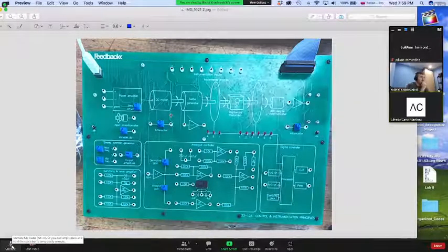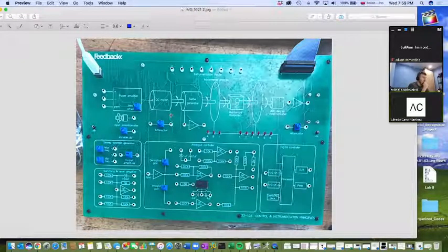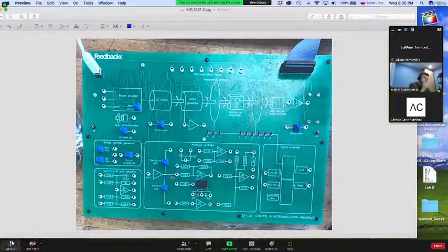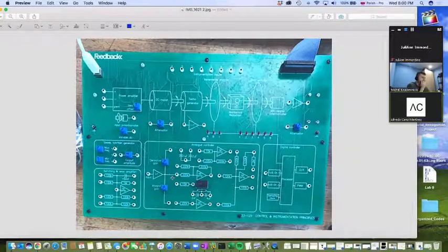So the summing and error amplifier, right? This you usually want to use simply to create the difference, or the error signal. Then you feed that into an additional component. It can be an attenuator, or it can be the circuit that you have in the middle of the analog controller. Yep. So usually, if you want to use the full PID, you want to use the analog controller